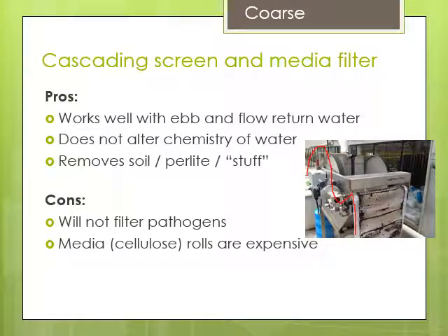As the water runs down into this hollow area, it percolates through to the bottom and gets filtered. And the debris, which collects on the paper, is slowly removed as the paper is rolled through the filter at a slow pace. I've got a video coming up that's going to help explain this.